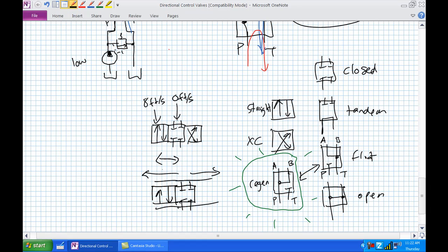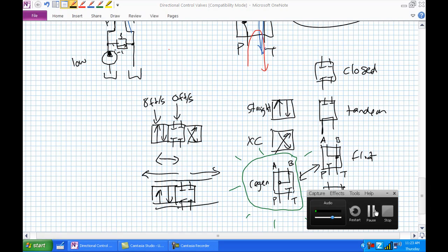Basically meaning that there is a variance, there's not just a full on and full off. There's full closed, then move it slowly, move it a little bit faster, move it medium speed, move it a little bit faster, move it all the way. That's a proportional valve. Sometimes you'll see this as basically a little joystick control, maybe on some load handling equipment, okay, just trying to gently move something out of the way, and then once you're clear of an object all the way, you can lift it all the way up, okay? So let's check here if I have covered everything on that subject before we move to the next one.